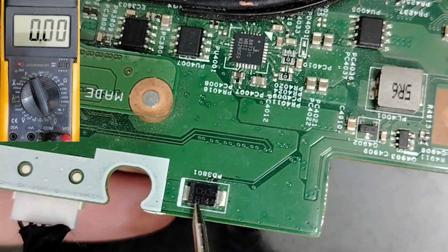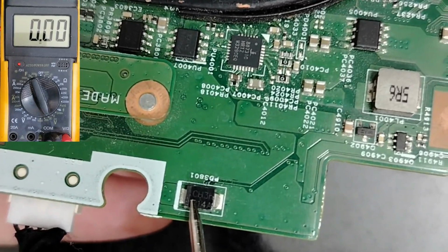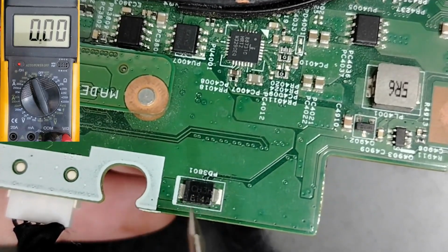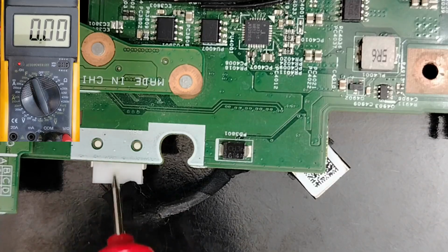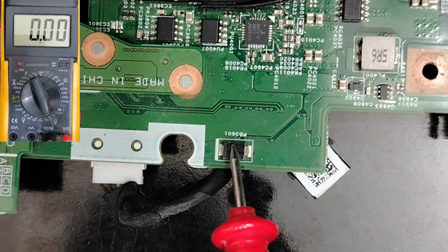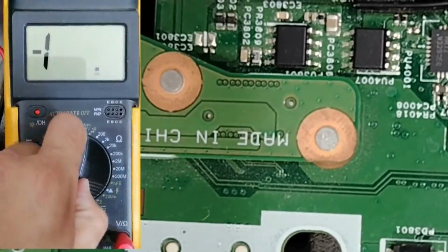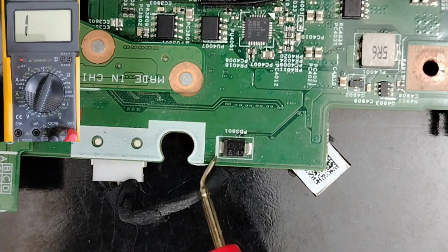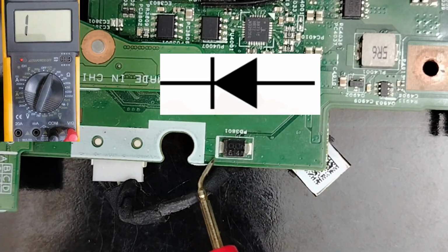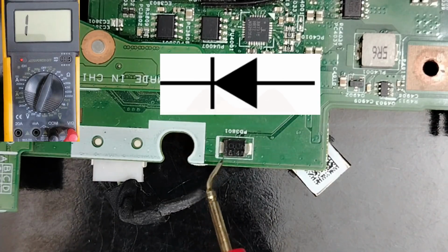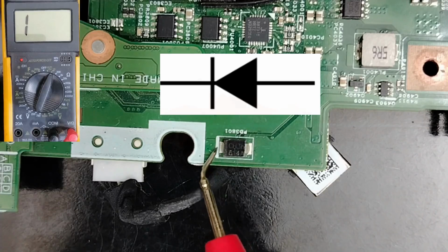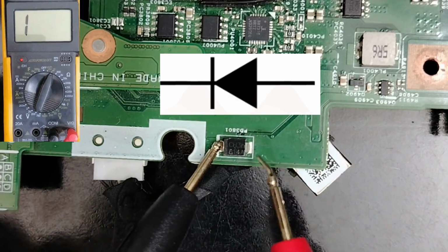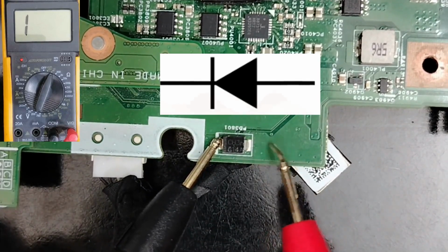You can test it using the continuity option or the diode option, or just check 19 volts here. Let's try both options. We have a flexible cable and the protection diode. Let's put the multimeter on the continuity option. Always locate the cathode. We have the cathode over here; this white mark or bar means this is the cathode. We put the black probe on the cathode, and the red probe on the positive terminal, the anode.